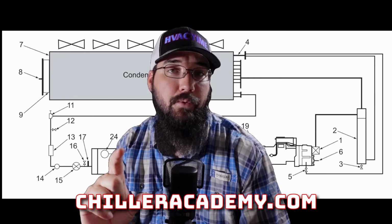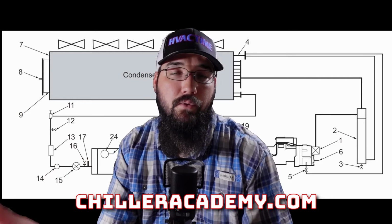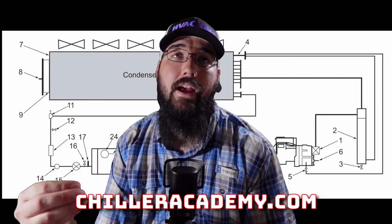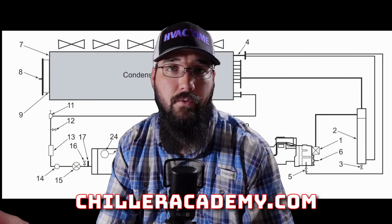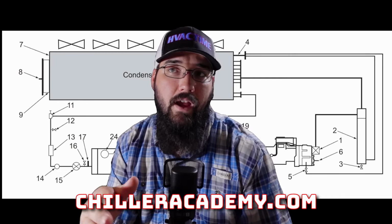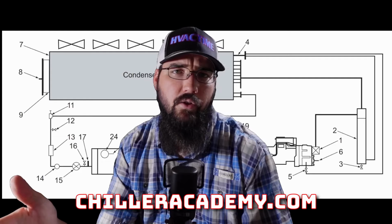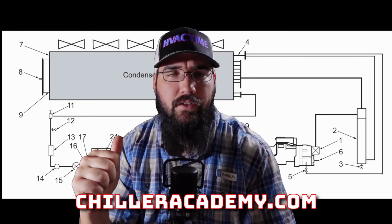Now, getting deeper into the compressor side, we're still going to be controlling our compressors based off of leaving water, which is going to have a PID, or just another term for an algorithm, in order to decide how much and how fast to ramp the compressor up or down in order to meet load on the leaving water side. So we're going to start off with a very basic example.